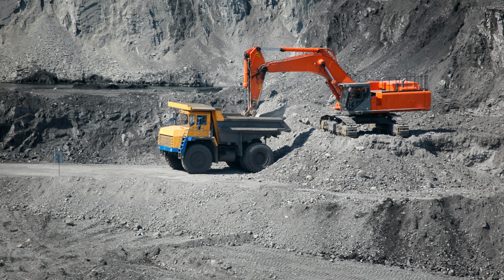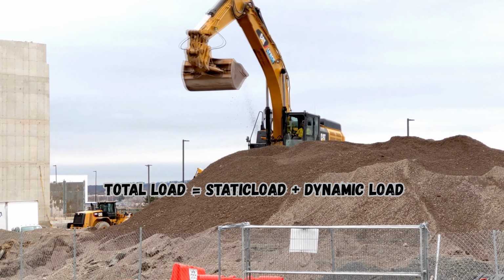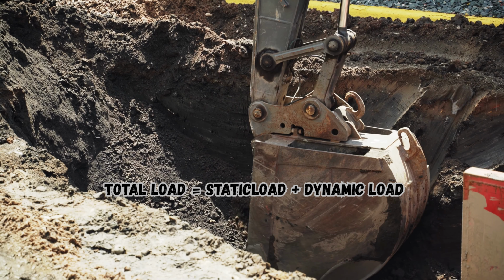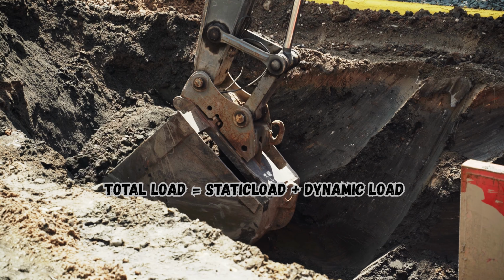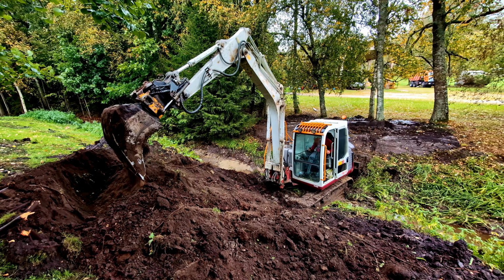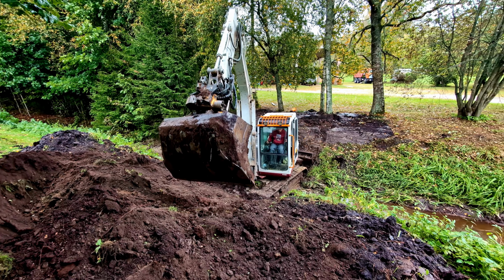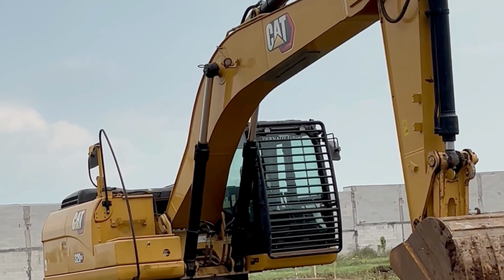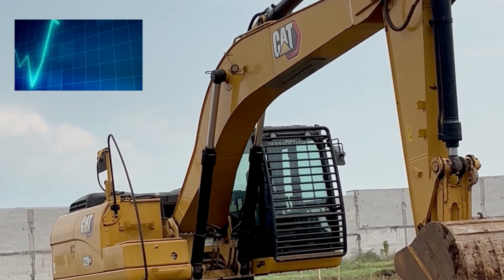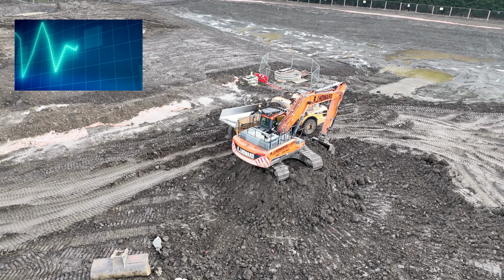If the excavator accelerates this mass during lifting or swinging, additional forces are introduced into the hydraulic system and structural components. These dynamic loads can cause pressure fluctuations in the hydraulic circuit because the hydraulic system must quickly respond to changes in load and motion. When the boom, arm, or bucket accelerates or decelerates, the hydraulic cylinders require rapid changes in oil flow and pressure. This can create temporary pressure spikes or variations within the hydraulic lines and valves.